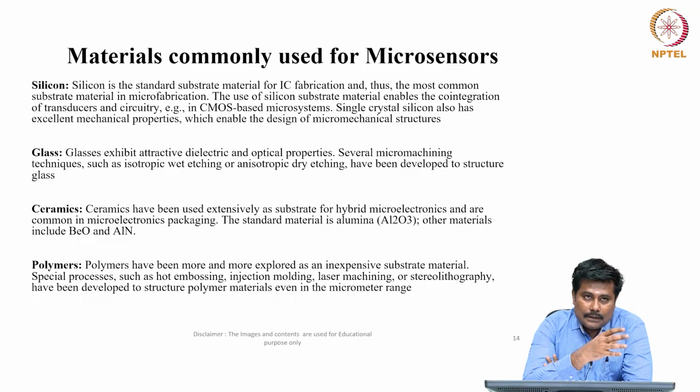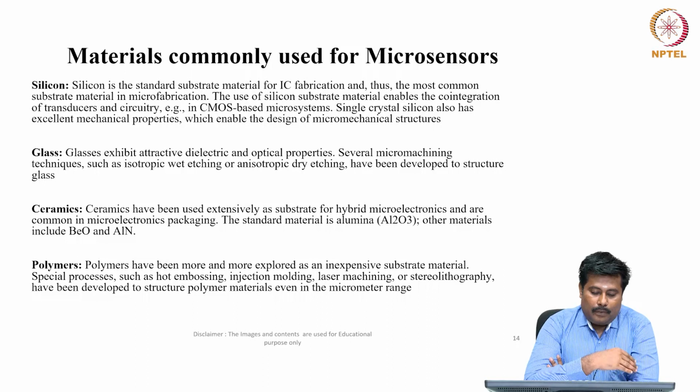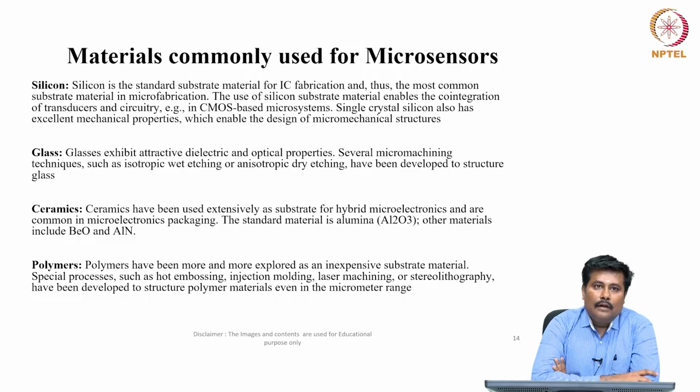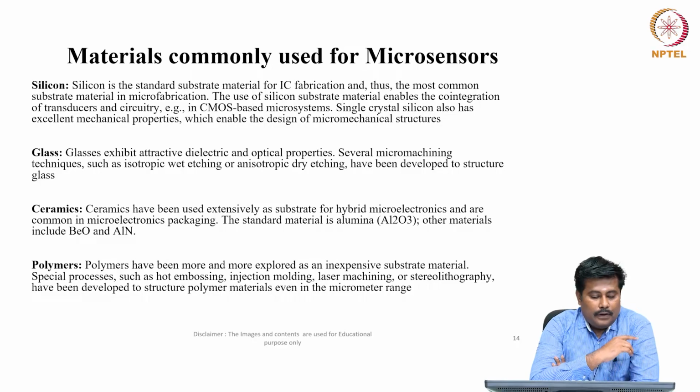So single crystal silicon has excellent mechanical properties which enable the design of these mechanical structures. When we talk about glasses, these glasses exhibit attractive dielectric and optical properties. Several micromachining techniques such as isotropic wet etching and anisotropic dry etching have been developed to structure glasses.